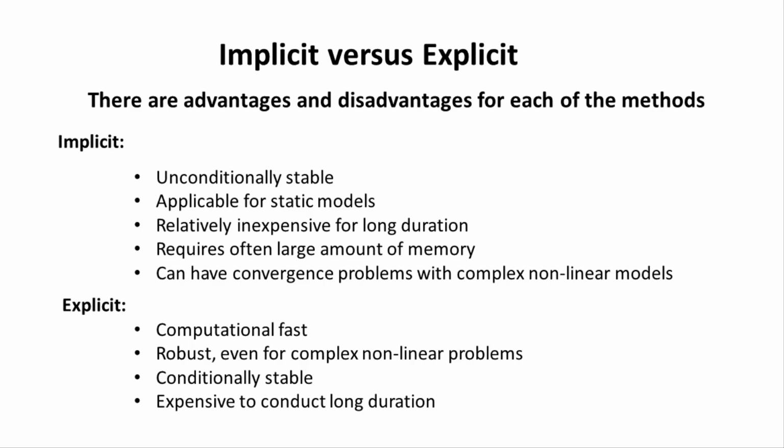Explicit analysis is computationally fast, robust, even for very complex nonlinear problems. But explicit analysis is conditionally stable and expensive to conduct for long time duration. I will show this later using a simple model.